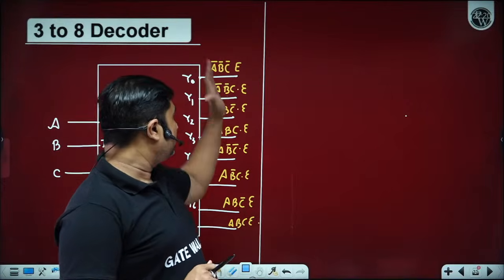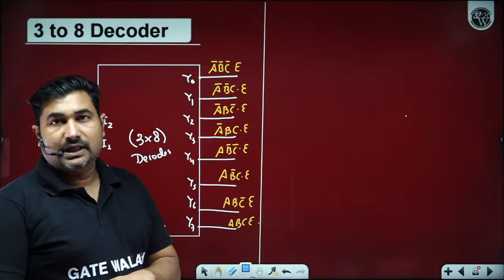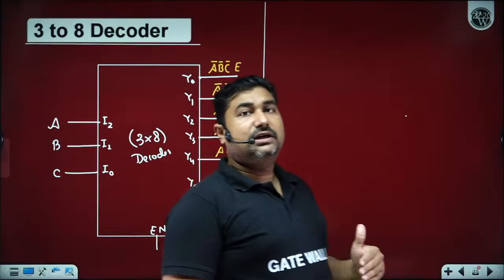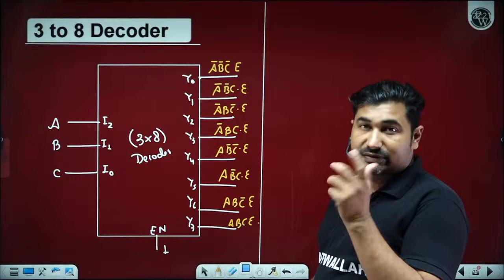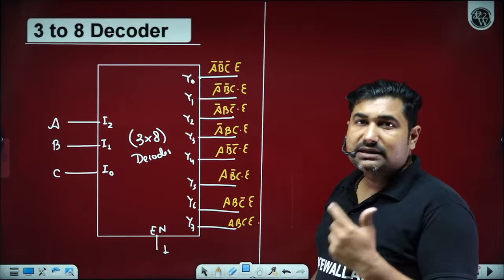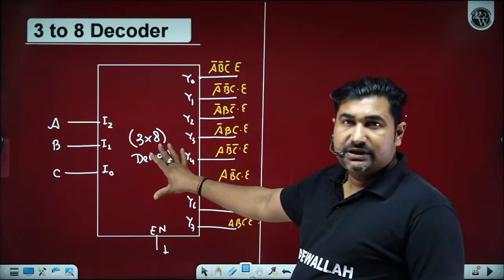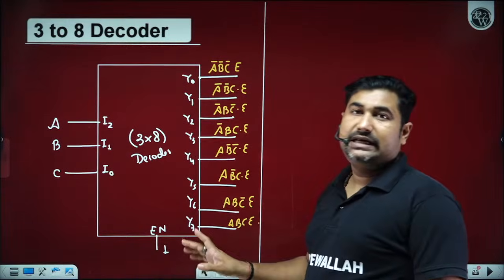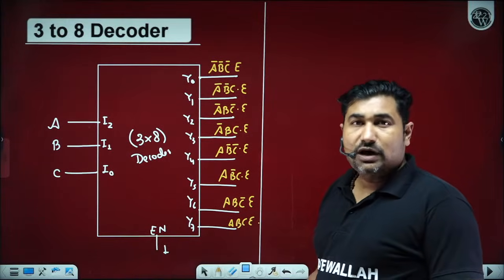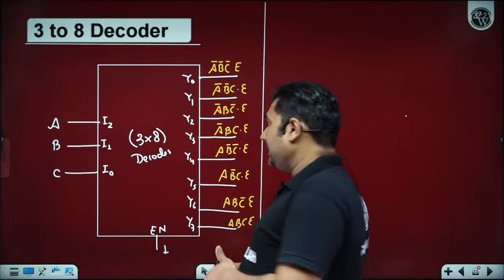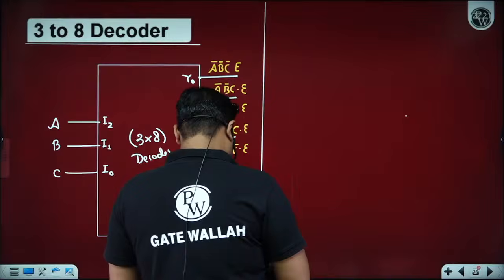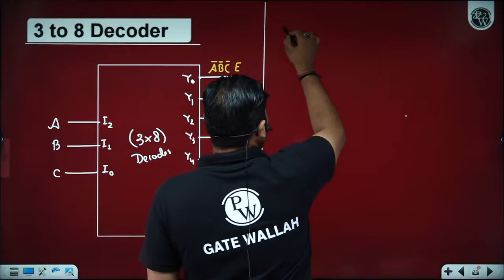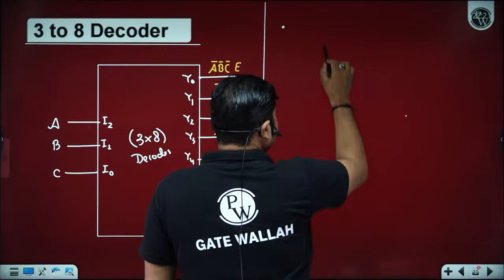It has nothing to do with the output bubbles. However, sometimes instead of using an AND gate, we prefer to design by NAND gate. Under such a condition, we can indicate the same decoder with each of the outputs indicated with a bubble. So what happens if the outputs are indicated with a bubble? Please observe here, beta ji.